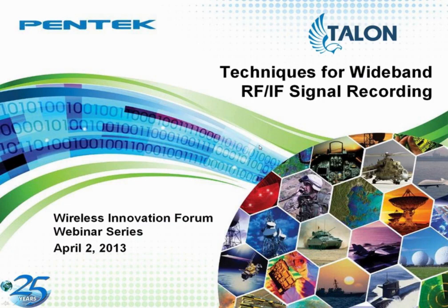First, we'll start with a basic view of what a software radio recorder system looks like. Usually we take the antenna signal, which is at the high RF frequency, and go through an RF tuner, which down converts that signal to a lower frequency that we can digitize with an A to D converter. The A to D converter then produces digital samples of the IF signal.